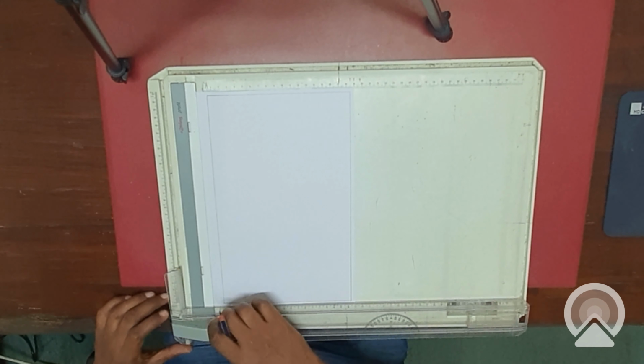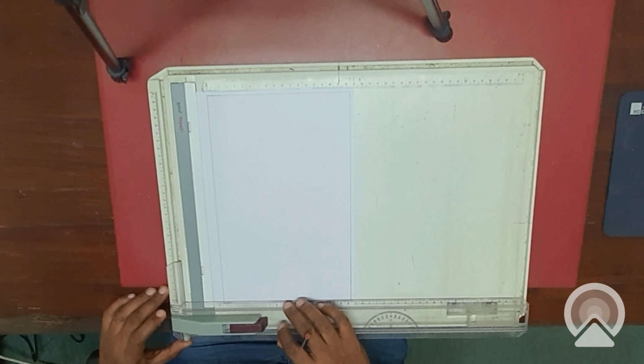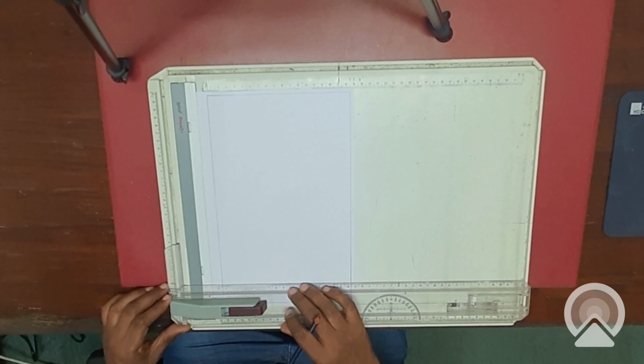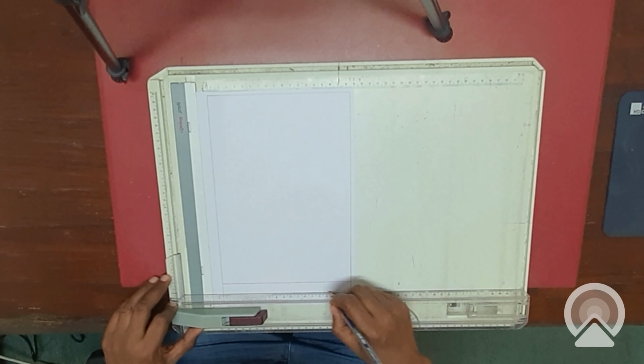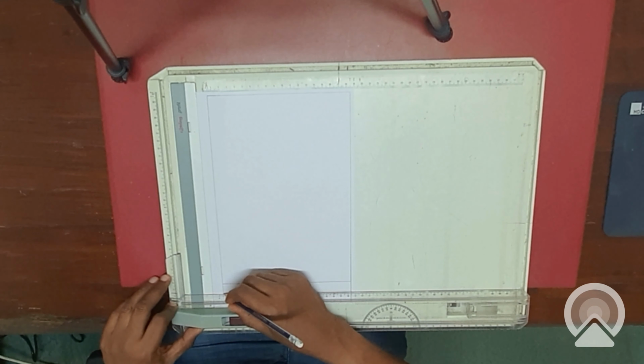Now you can add your title block. We know the size of the title block is 30 millimeters from below. So we start with the lower margin at 0. That means at 3 centimeters or 30 millimeters is where the end of my title block is. And at the middle, that is 1.5 centimeters or 15 millimeters, I have another horizontal line here.